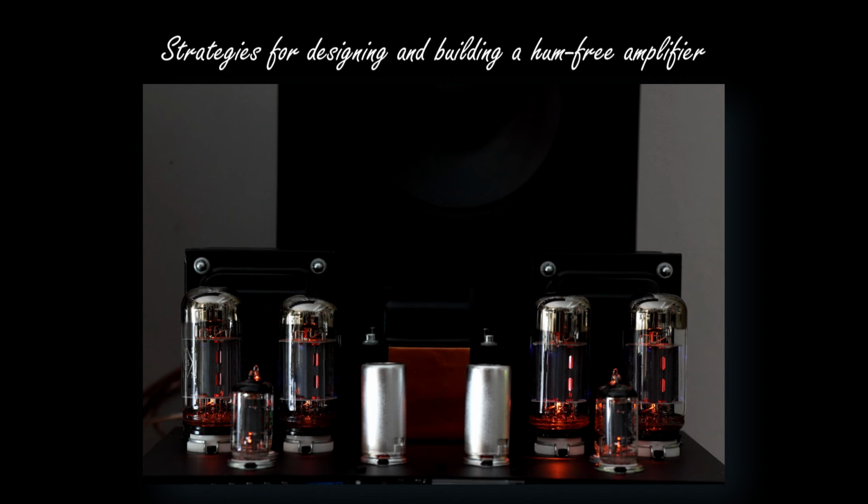Also, it's very useful to implement a magnetic shield on the power transformer. You can see an example here. This copper strip is a shield which highly reduces the electromagnetic field radiated by the power transformer. In all my projects, I do the same on the smoothing impedance as well.